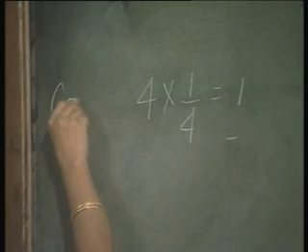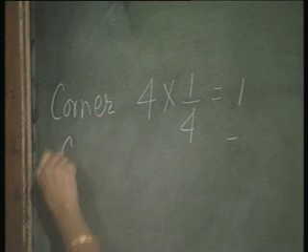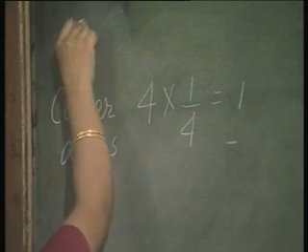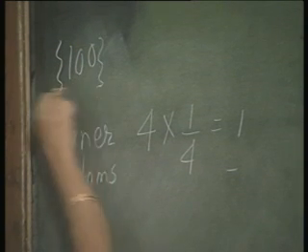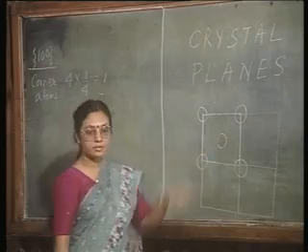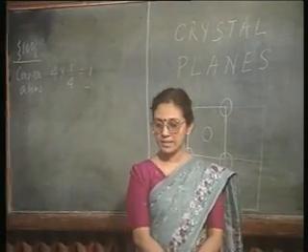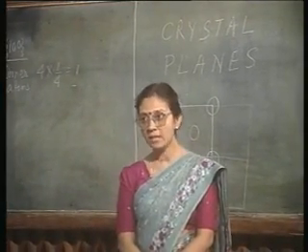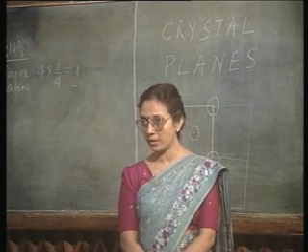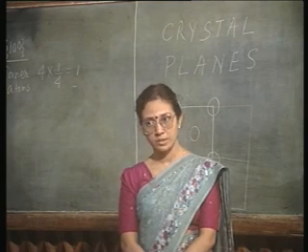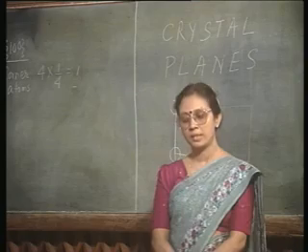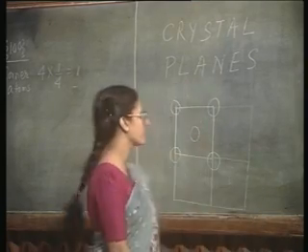This is the contribution of the corner atoms. What about the center atom? This is uniquely contained in one 1 0 0 plane. It cannot be shared by other 1 0 0 planes. Therefore, its contribution to the 1 0 0 plane is unity, it is 1.